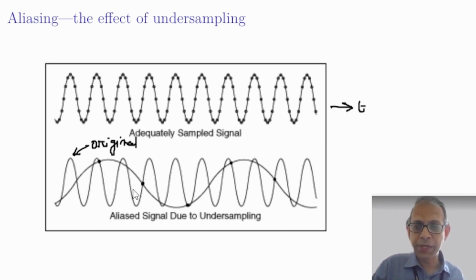For the Nyquist rate, we should take at least 2 samples per cycle, but here we are taking 2 samples in 4 cycles, and therefore the sampling rate is sufficiently smaller. This is the case of undersampling.